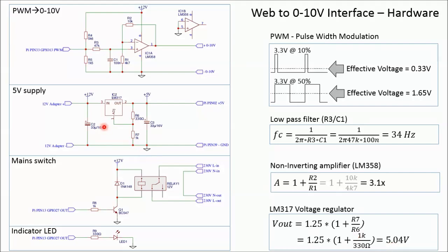The LM317 is protected against overheating and short circuit. It is recommended to add a capacitor on both the input and the output for regulation stability. I will include the datasheet of the LM317 in the data file, of which you can find the link in my comments. The 5 volt here is directly connected to the Raspberry Pi's 5 volt pin of the GPIO.